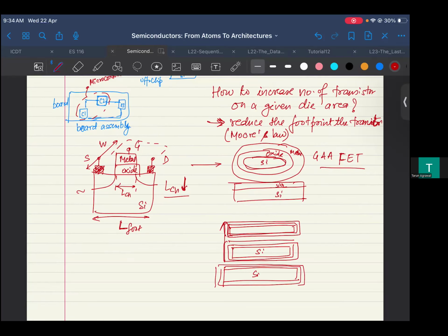So you see that you are already now going towards 3D, right? So the transistor itself becomes 3D, because now this whole thing is what I call one transistor, which has turned 3D. The reason is because I'm trying to get the transistor performance increased within that area, right? Because the footprint has not changed.